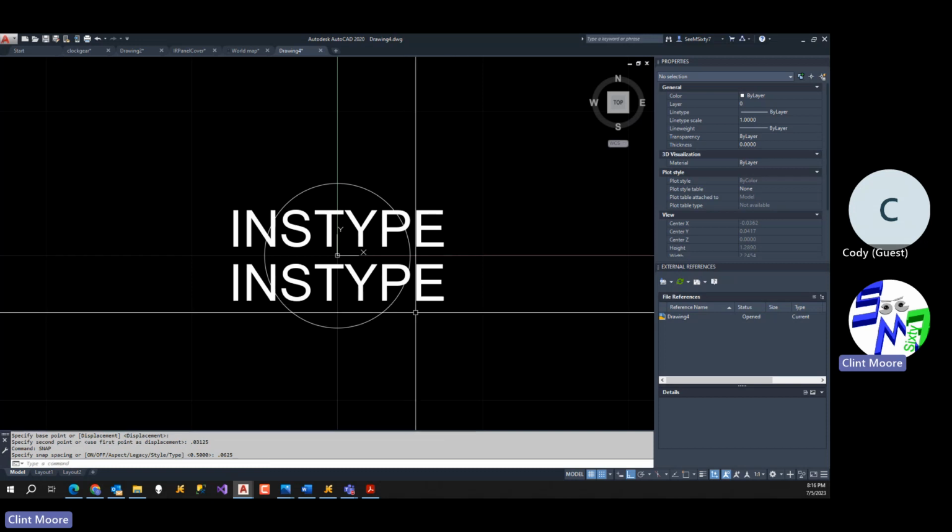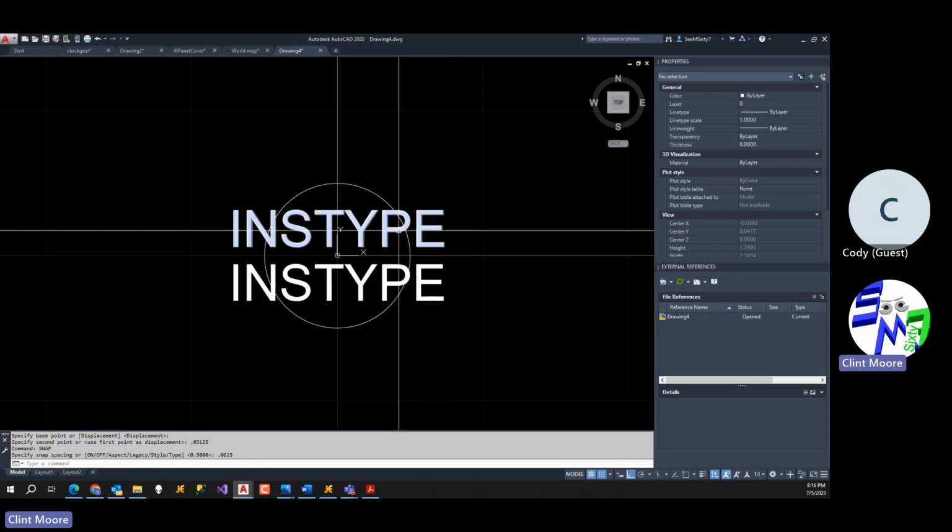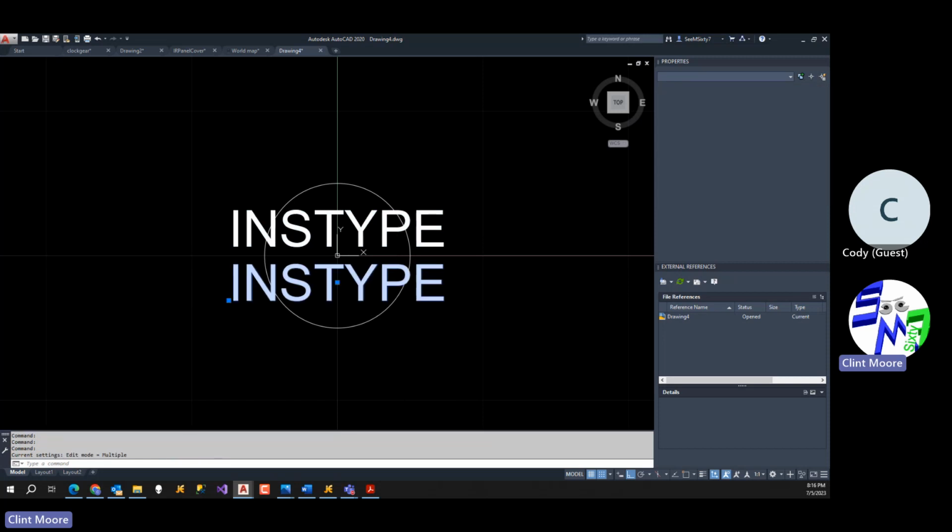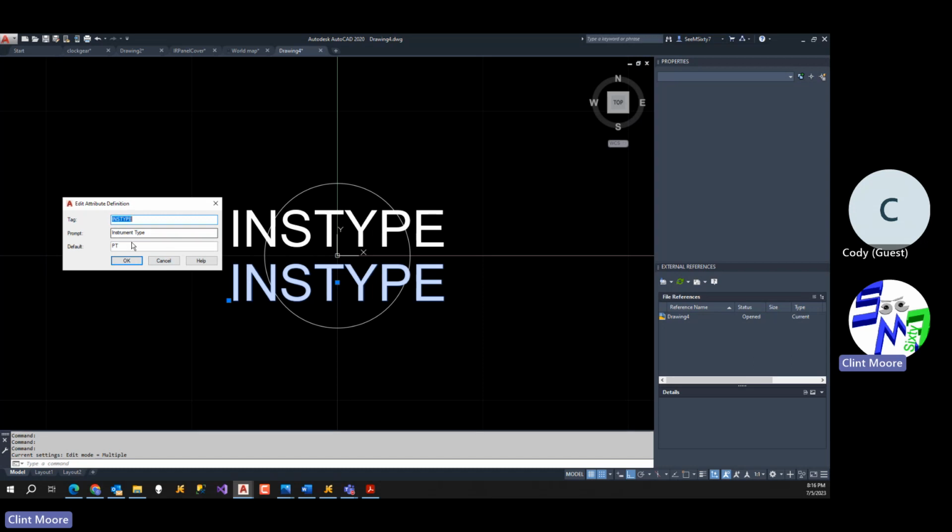I've created my bubble, but I've created one type here, but I need to change this attribute definition to be a little something more consistent. I'm going to move this over here. I double clicked on it to pop up the attribute definition dialog box. And this one's going to be my tag. So I'm just going to simply go INS and then tag. Change that over there, and I'll type in tag. I'm going to give it a default of 1001, just for something to show up as a default.